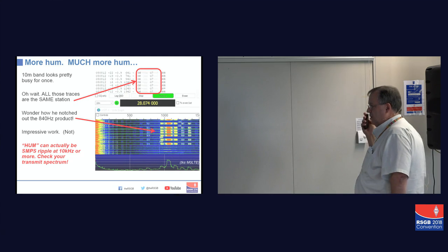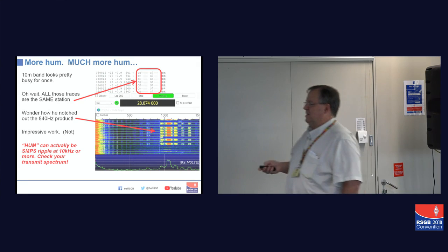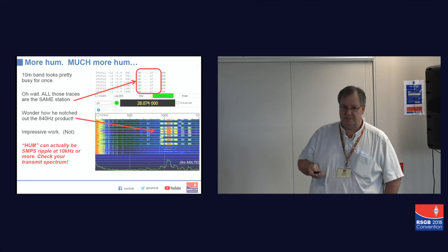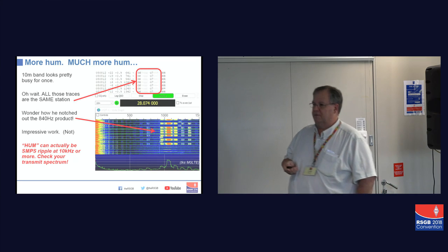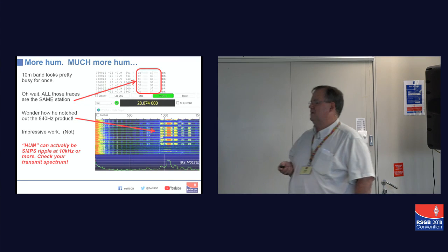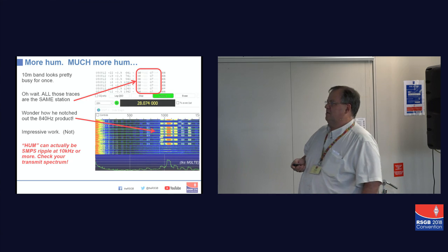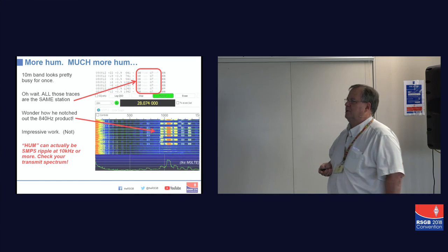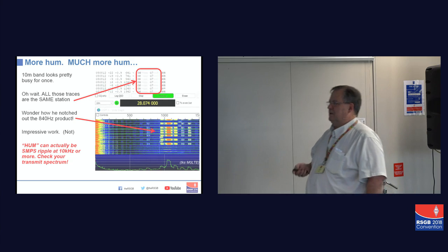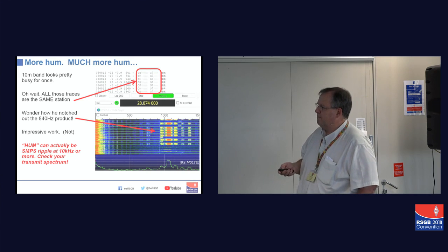The other thing you've got to watch is hum can actually be at 10 kilohertz from your switch mode power supply or whatever. I was caught out by that on 3 centimeters. I was transmitting away and somebody said, you're also 15 kilohertz up and 15 kilohertz down and 30 kilohertz up. So found out that my switch mode power supply had gone a bit wonky.